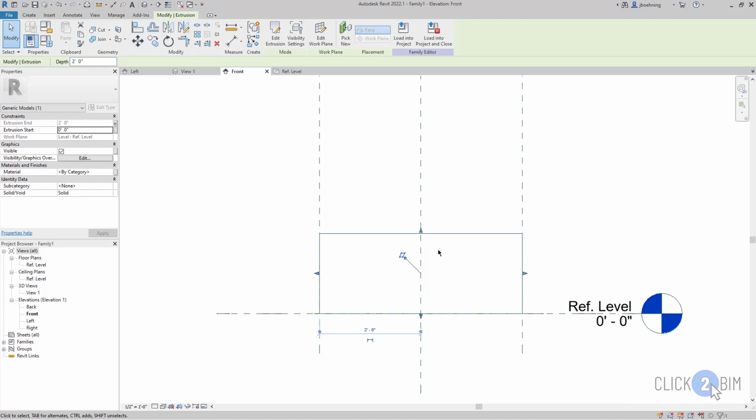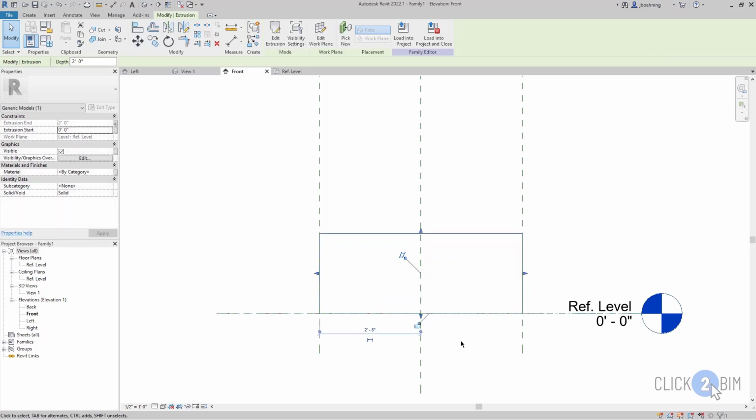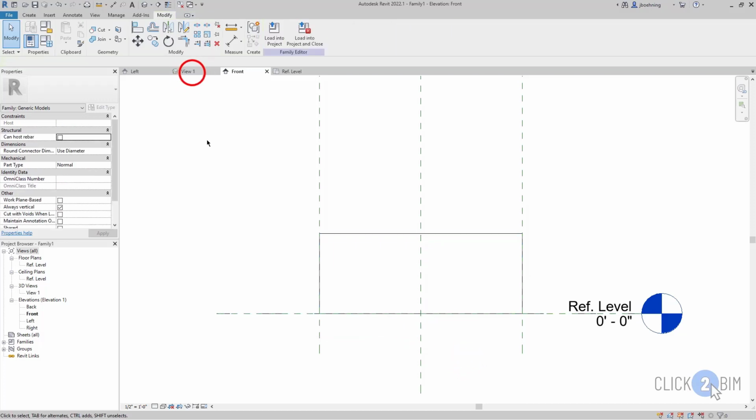And just a quick note, if you go that route, or really either route you go, you also want to make sure that the bottom is constrained in some way. And you never want to leave it up to chance on how that's going to be controlled. So what I can do is simply drag it down to the bottom to our reference level here, or if we had another reference plane. And when you do that, but more specifically when you snap it to the reference level or a reference plane, you'll see that padlock icon, and you can simply click that to lock it.